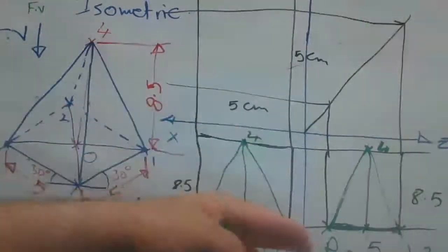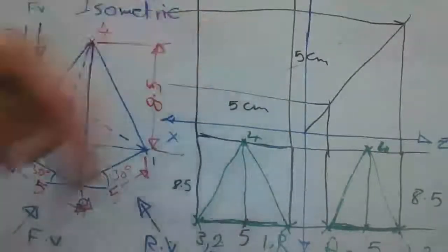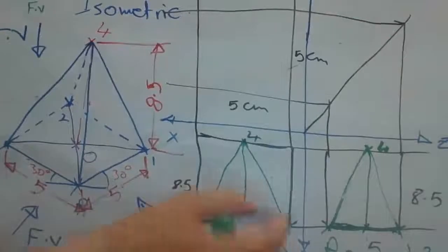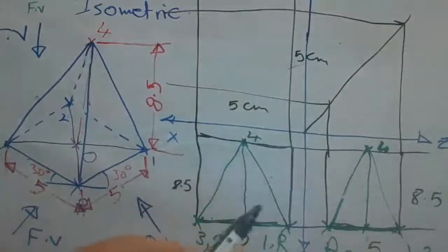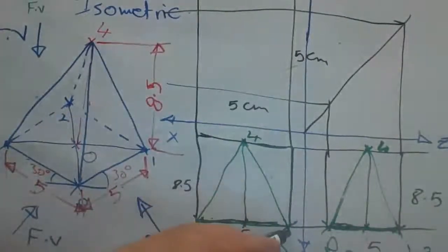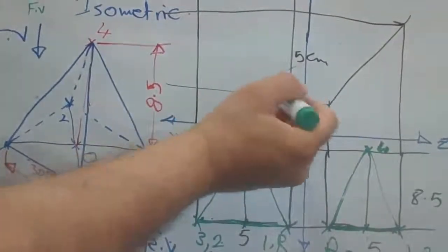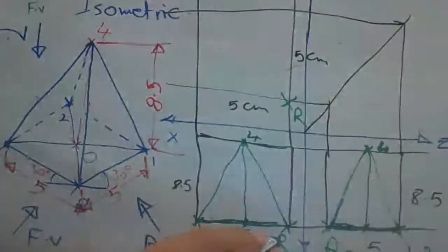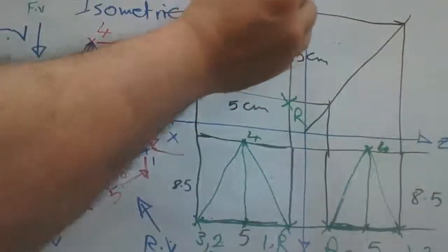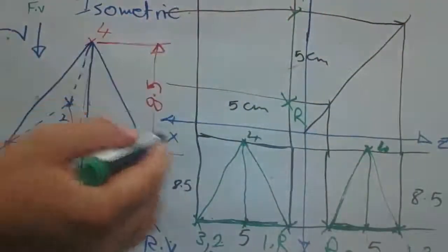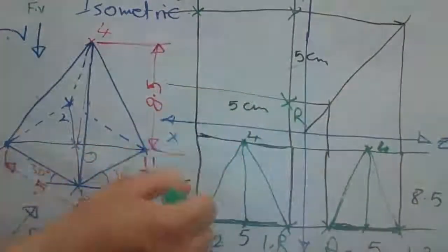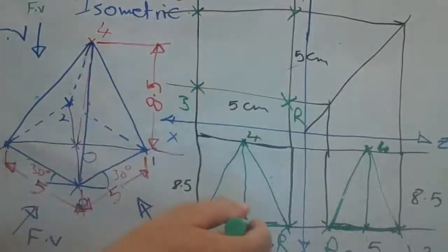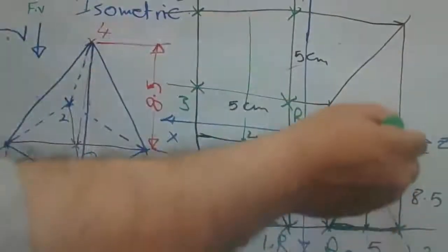So now if we go to draw the top view, if we choose point by point or as a full shape, we have two choices. If we follow one point by one point, R and R here, one from here and one from here, so 1 becomes here, 2 from here and 2 from here, we find 2 here, 3 and 3, 4 from here and 4 from here.